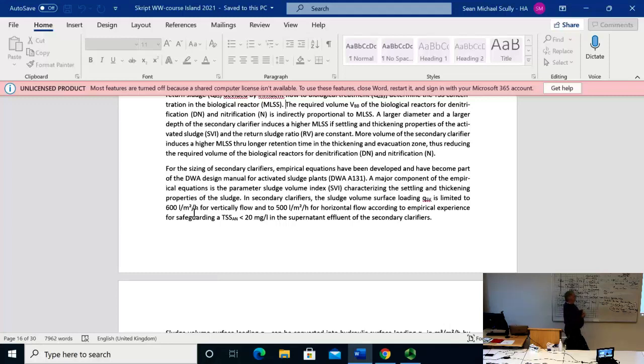So this, times 175 times 0.503, gives us roughly some 90 liters of sludge per person and day. Well, it's 88 exactly liters of sludge per person and day. And divide that by 24. Well, normally, for peak water, we have to divide it by 16 or something.